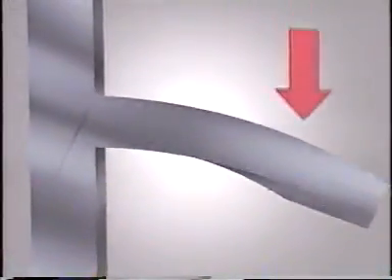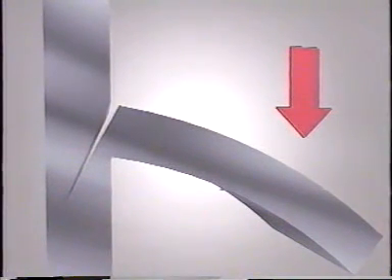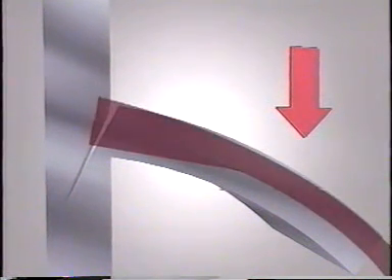At low stress levels, only one origin is usually found. A related form of loading is cantilever loading. Here, the bending moment varies along the length of the beam. This means that the tensile fiber stress will also vary along the length of the beam. Fracture will initiate at the point of highest stress, usually adjacent to the rigid mounting, depending on the shape of the beam.